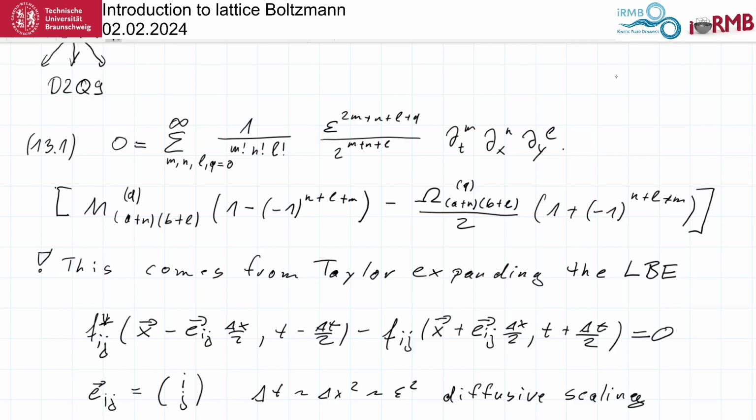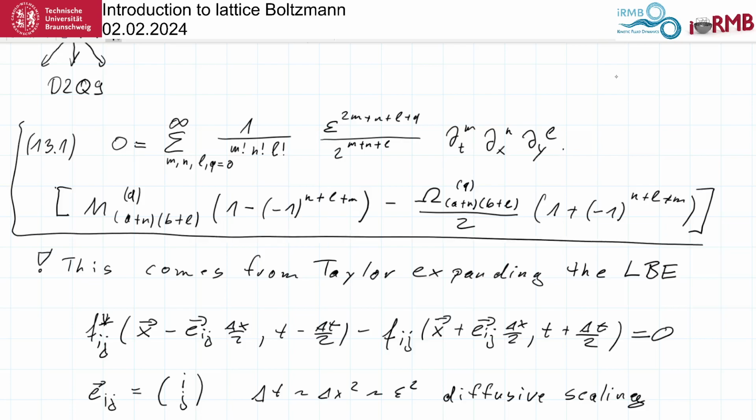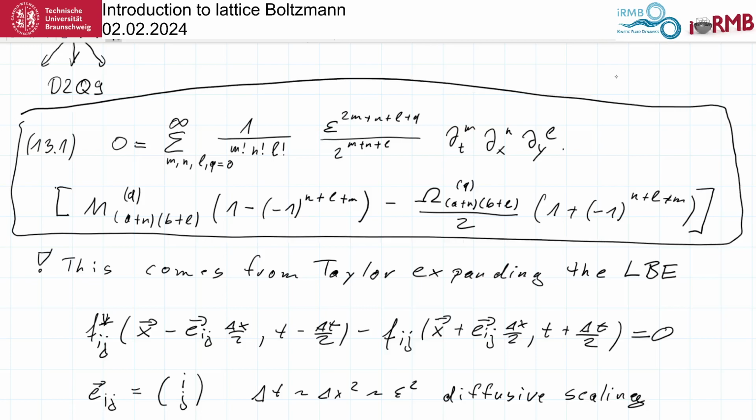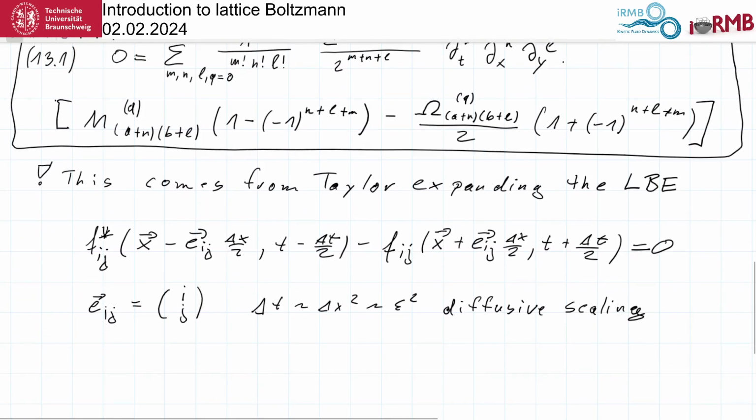Okay, Taylor expanding this and taking the moments leads to this big equation that we need to actually derive lattice Boltzmann methods. So we have interpreted this in previous lectures, now we are just going to use it, accepting it the way it is. So, in addition to Taylor expanding, we also have the asymptotic expansion of the moments, here indicated by the q's. Okay, we will combine this with the relaxation time ansatz.